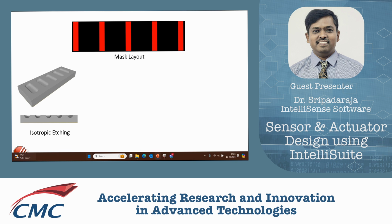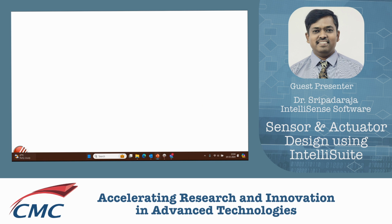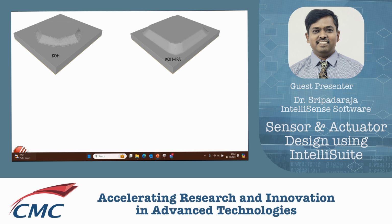This is a good example of how the same mask can be used for achieving various etch profiles like the isotropic etch, anisotropic etch, and plasma etching. So various shapes can be achieved, and based on that, we choose the etching parameter.